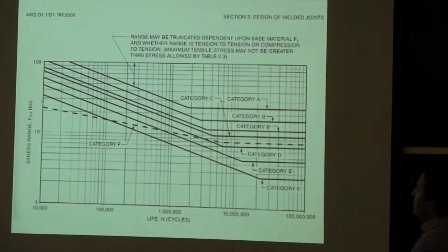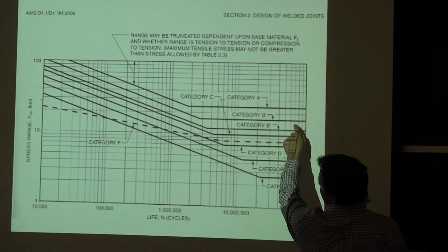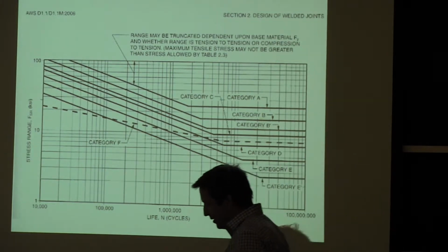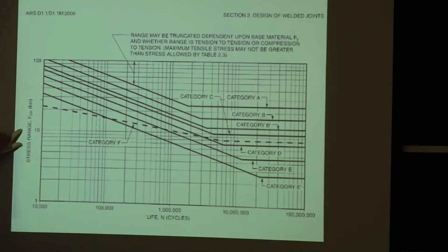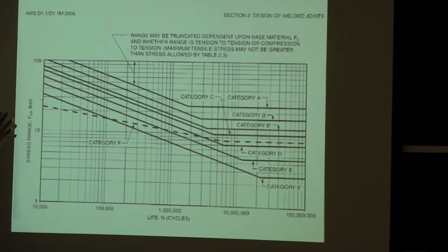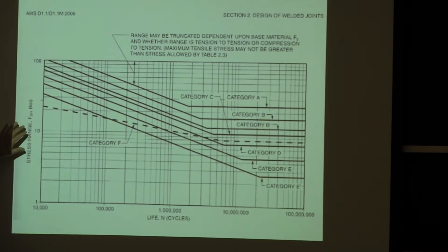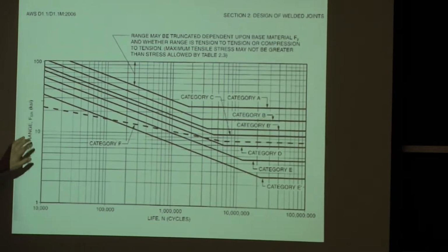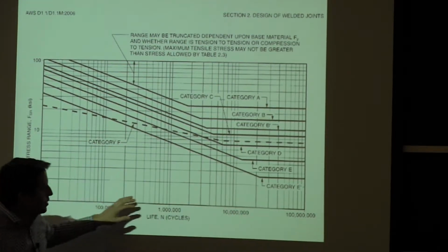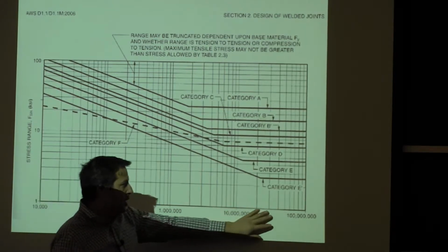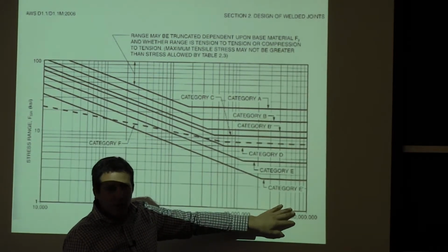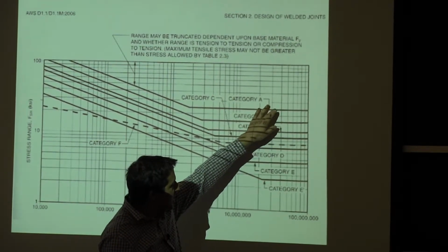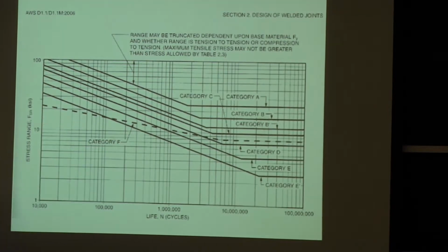What you can see between the base material here, you have an allowable stress range. So we're talking about fatigue here. This is slightly different, where the stress range is essentially your maximum stress minus your minimum stress. It's not the amplitude, the amplitude will be half of this axis. And the life here is what you allow to tolerate. So if we're looking at something that would be under vibration condition, or we don't know how many cycles we get, we'd be looking here at the base material being above 20 KSI, and then the alloy, if it's a